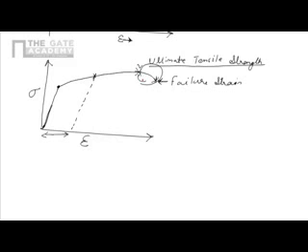There are various grades and alloys of steel, and they have different values of the yield point. This is the yield point, which I mark as YP, this is the UTS, and the failure strain. The yield point, UTS, and failure strain change from alloy to alloy. The E value is almost equal for all the alloys.